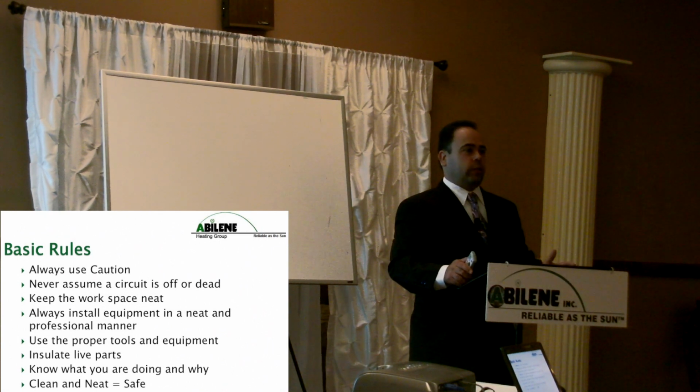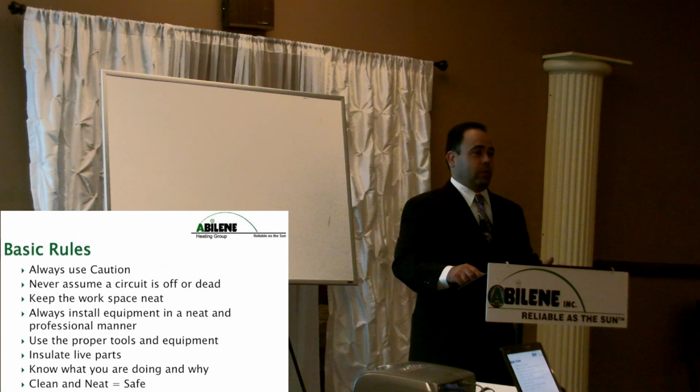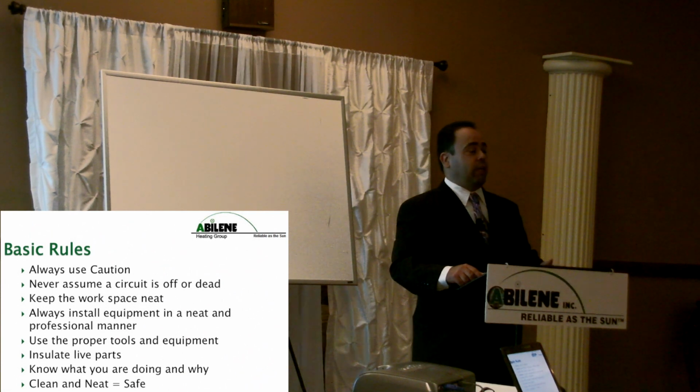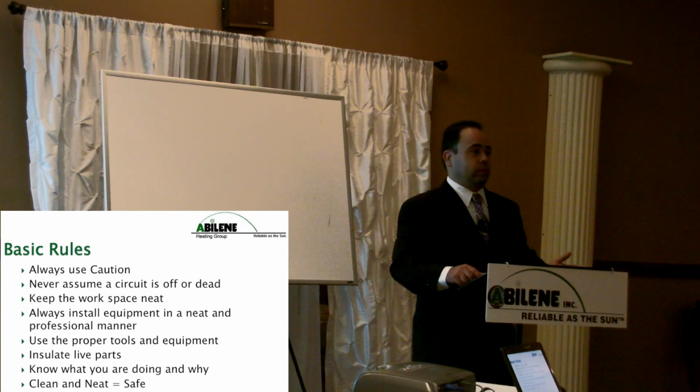When you're dealing with electric, it has to be neat and clean, because if it's a mess, you'll never be able to trace it. You'll never know what's live, what's dead. All right? And then you're going to get confused. If it's neat, straight, and simple, it's easier to trace. It's easier to troubleshoot. All right? Everyone get that? I mean, that's pretty simple, basic, right? Hector?